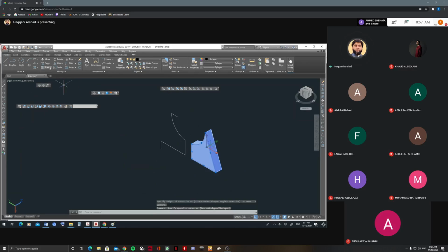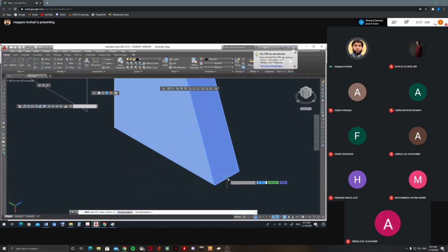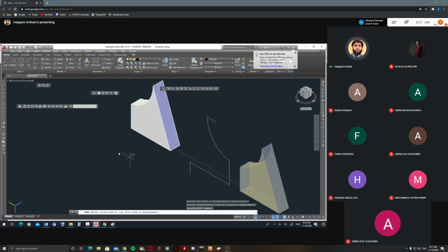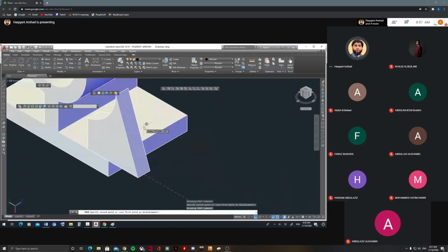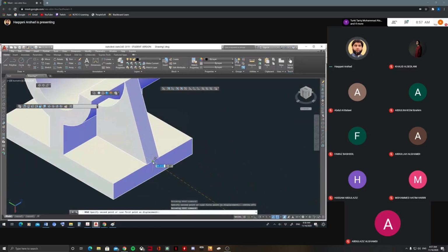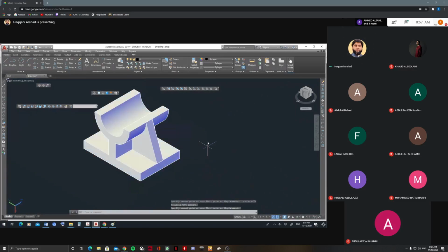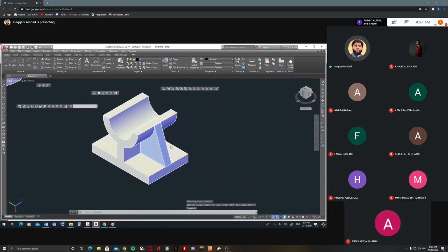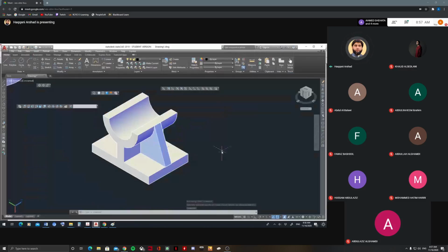That's it. So now you can move it. Simply use the move command from this center midpoint, and you can move it to here in the middle, exactly to the midpoint of the base, top of it, like this. You got it there. This is on the other side as well, but in the figure it is not shown. So it is also available on the other side.